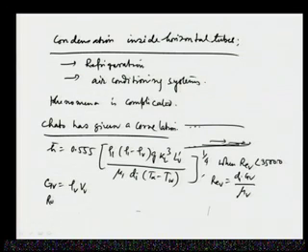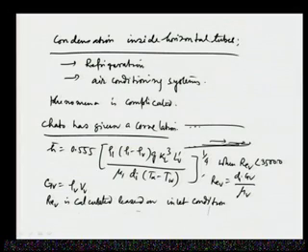That Reynolds number ReV is calculated based on the inlet condition of the vapor and the inside diameter of the tube. One important thing is that as it flows through the inside diameter, the available diameter for the vapor flow is less, because some of it is covered by the liquid, but that is neglected.